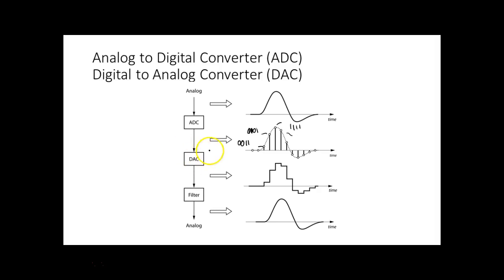What we do when we go to an analog to digital, is basically we take a waveform, we take a binary number, and we convert it into a step size. So what you end up with, your actual analog output is going to be a sequence of steps. So it's still not pure analog, right? You understand? It's going to be steps, right? Does that make sense? And I wish I had my digital scope over here. We could actually see the steps on the digital scope, because it's taking an analog input and converting it over to a digital representation. We can filter it out a little bit and make it look kind of neat.